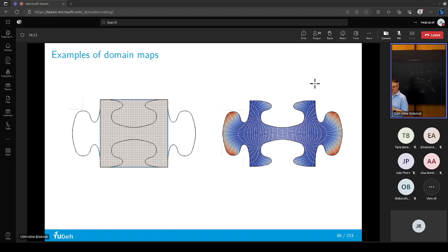It's also a big problem. And there's a conservation of, what is it, misery. It's a big problem. And also, this is one of the most standard ways of creating a parametrization. The technique that I just mentioned, what it is, we do harmonic mapping. What is harmonic mapping? Something like elliptic grid generation. We solve a nonlinear Poisson type problem just to get the mesh for solving the Navier-Stokes. But okay, if you want high resolution, you need to pay somewhere.